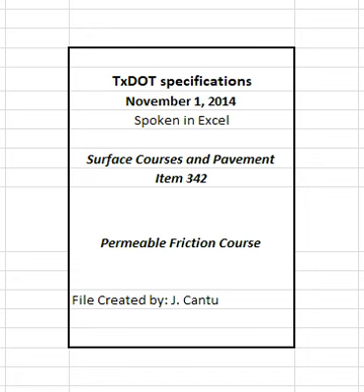5.1.1 Target percentage. The JMF target asphalt percentage will be used to calculate the weight of asphalt binder unless the measured asphalt binder percentage is more than 0.3 percentage points below the JMF target asphalt percentage or less than the minimum percentage specified in Table 4. Volumetric meter readings will be adjusted to 140 degrees Fahrenheit and converted to weight.